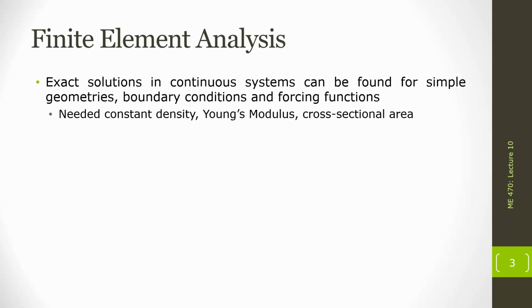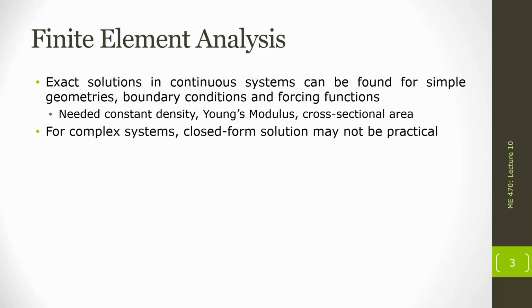On top of that, we might not be able to deal with a change of density or Young's modulus or cross-sectional area, because the PDEs that we came up with that we were able to solve by hand required these to be constant. And if one or many of them were not constant, we would have gotten a more complicated partial differential equation that might not have a closed form solution that we can obtain. Once we get to any problem that becomes a little bit more complex, a little bit more interesting, we might not be able to get a closed form solution, or it might be very difficult to achieve one.